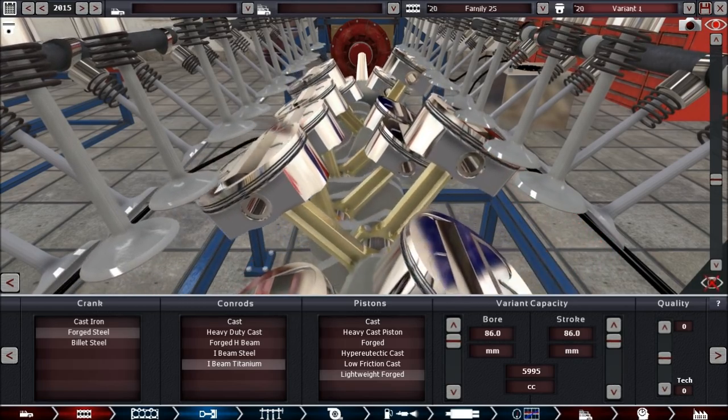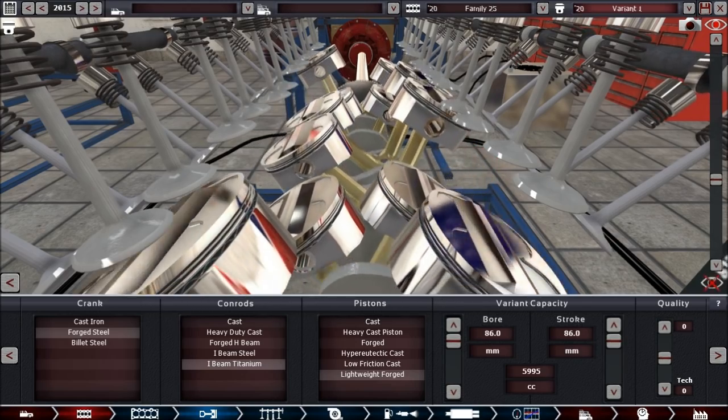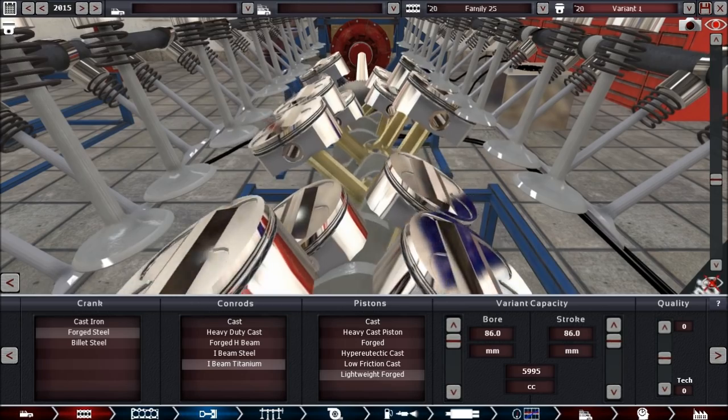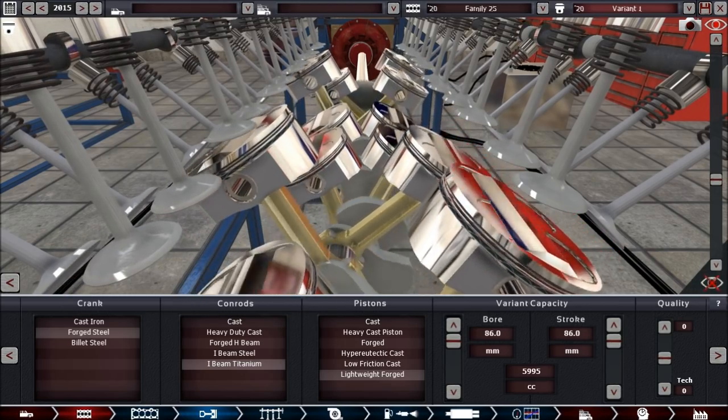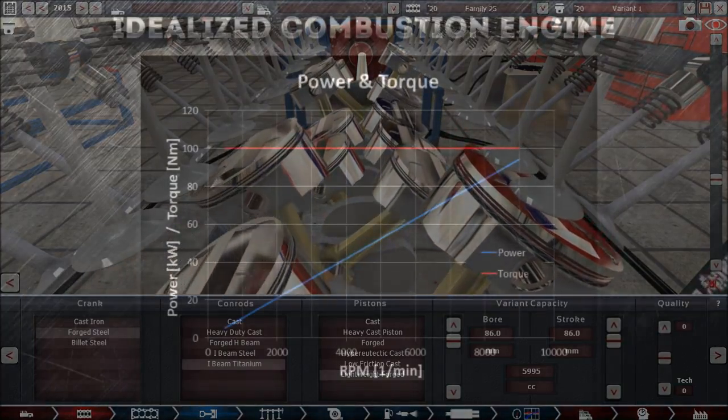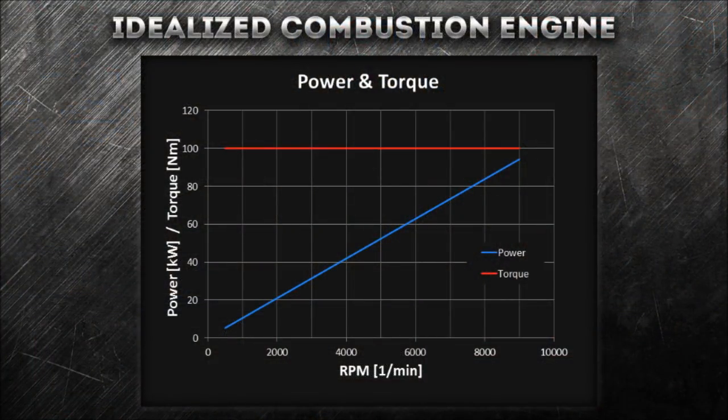Also worth noting is that from what we have derived, it directly follows that you would want to rev this engine as high as you can at all times in order to get the maximum acceleration out of it. You would want to gear it such that it revs as high as possible to make the maximum power. Real-life engines have a lot of problems revving higher and higher while keeping up producing the same amount of energy per combustion cycle. A gearbox is needed to help work around this limitation.